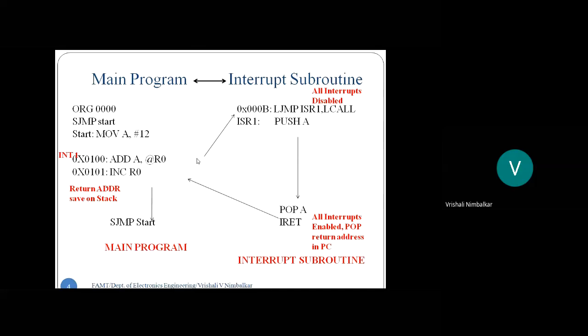Okay, so no doubt when the microcontroller jumps to the vector address, it will first disable all the interrupts, and the programmer will write one jump instruction, jump to the actual position where the ISR is written. And then at that label, we write the actual ISR.